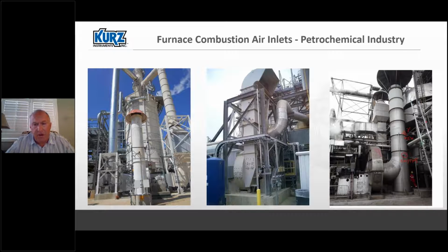And that's when I started thinking about some of the problems I'd had in the past with moisture on ambient air inlets, as well as with dirt contaminants on ambient air inlets. I had several refineries complaining about these air inlet applications where they would have to clean the sensors quite often, and they were also getting noisy results in rainy events.